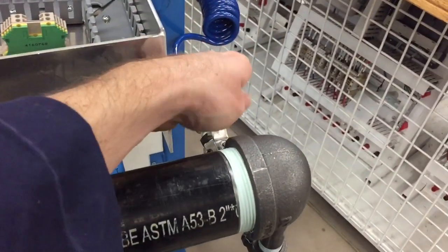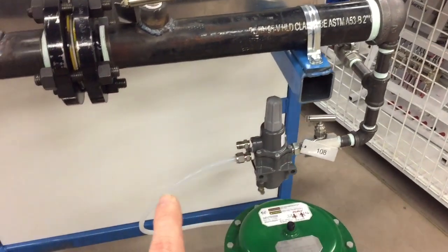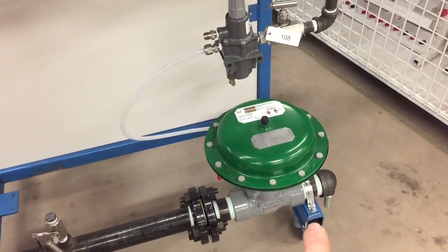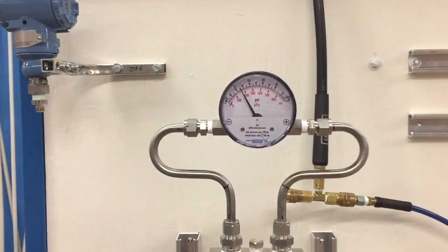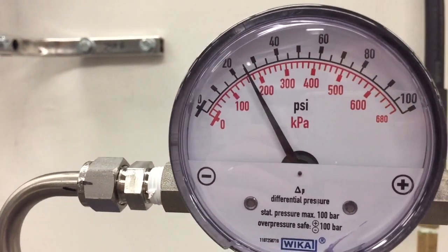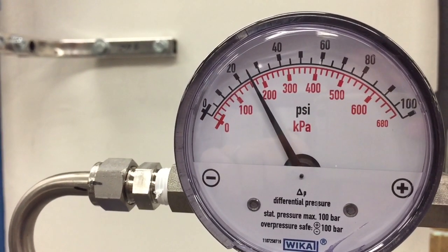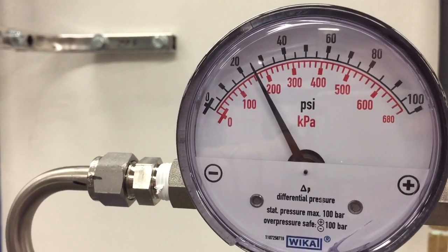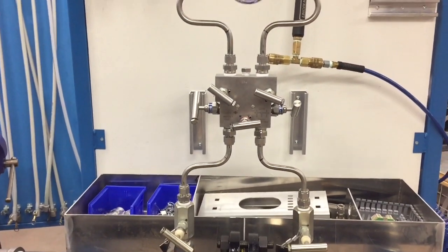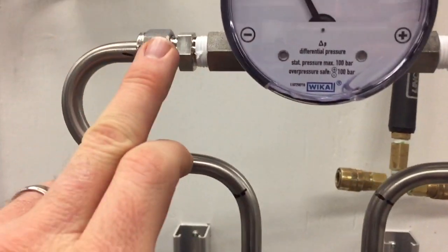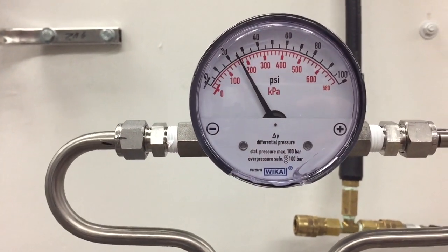All right, now that I've connected instrument air over here on the back side, I have air coming in, going through this regulator, opening our control valve at the bottom here, and then air is flowing out the bottom. And if you look at our gauge here, we're registering a differential pressure of about 25 psi, or about 175 kPa, on the differential pressure gauge. So it was plumbed in right. If we had these tubing lines switched, we'd be reading a negative pressure.